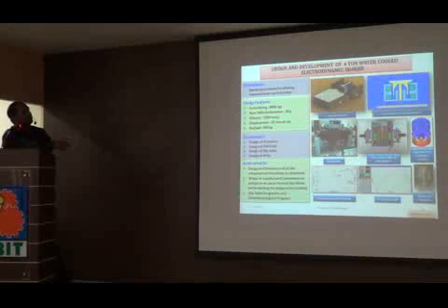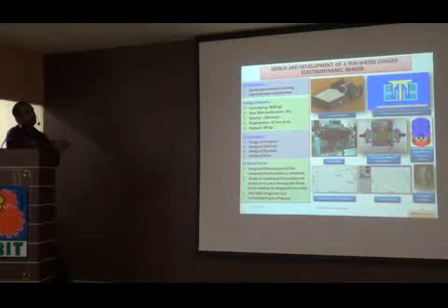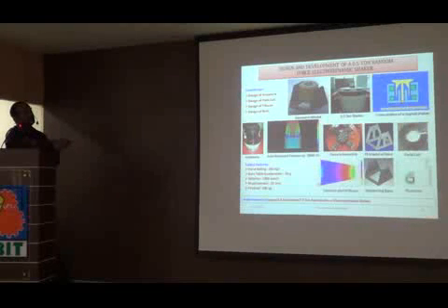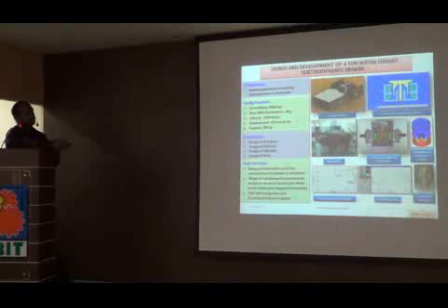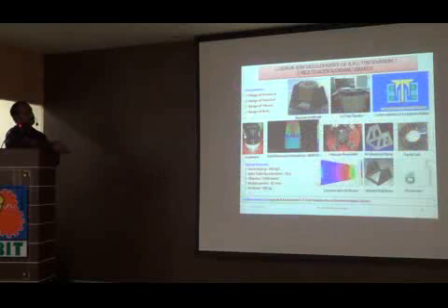Apart from the air cooled shaker, we also developed a water cooled shaker to demonstrate the technology. The same concept applies here, except that it is water cooled. Water cooled here means that in the armature, water is flowing in the same hollow conductor in which the current is also flowing. That is the criticality. Here, what happens? The conductor, whatever we used for this, is a solid conductor.